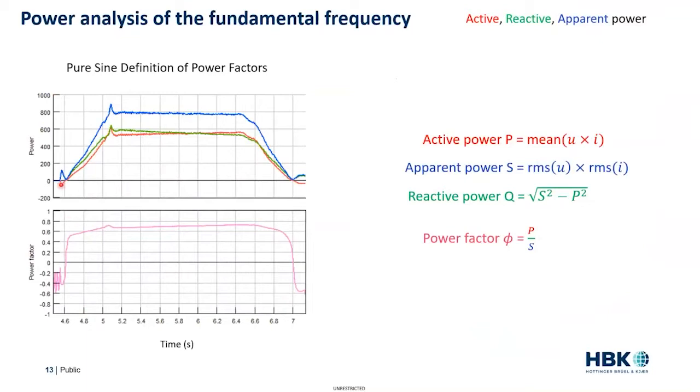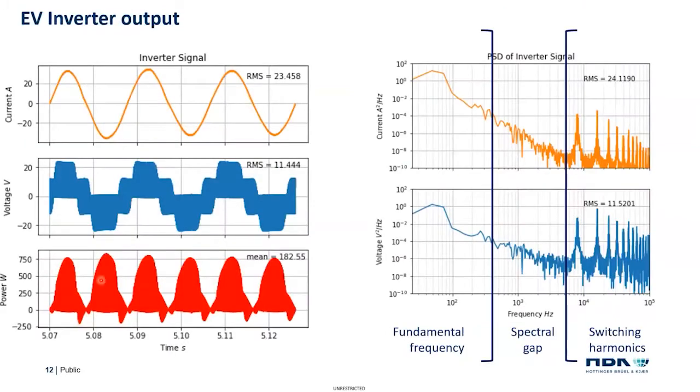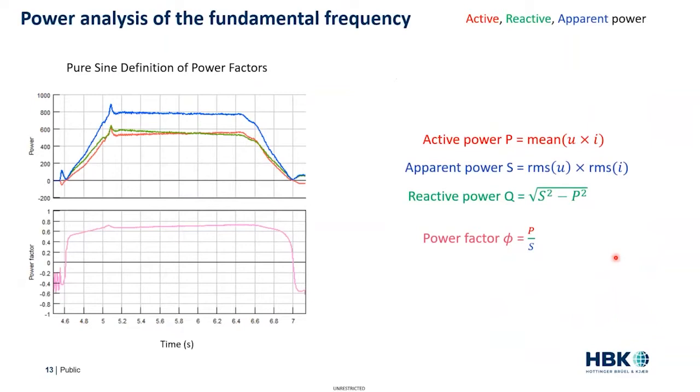And the problem that we've got here is when we look at this, because they're non-sinusoidal, it looks like the reactive power is very high compared to the active power. In fact, the reactive seems to be bigger here than the active power. And this doesn't really stack up to what we're seeing in this diagram here. And the reason it appears wrong is because these simple equations, they're not accounting for the differences in these high frequencies. They're assuming that they're perfectly sinusoidal.